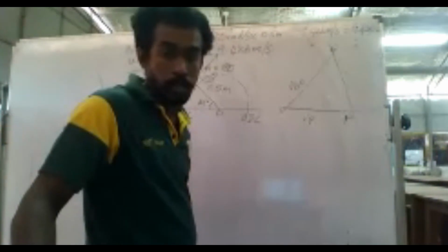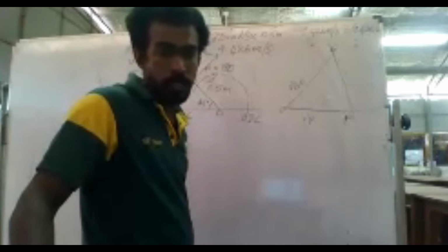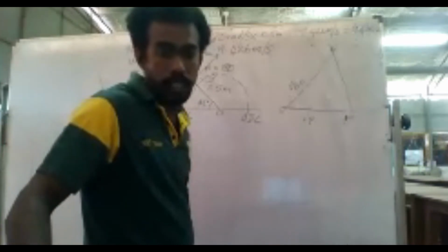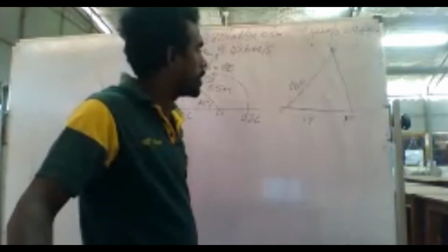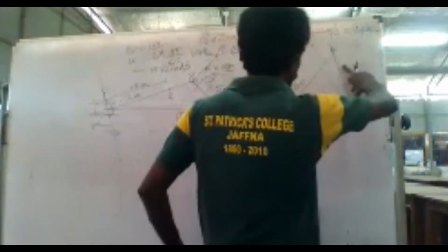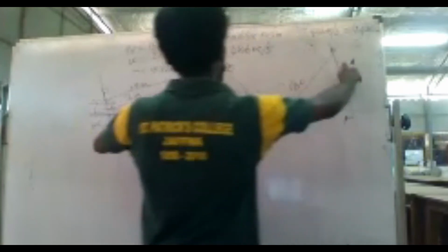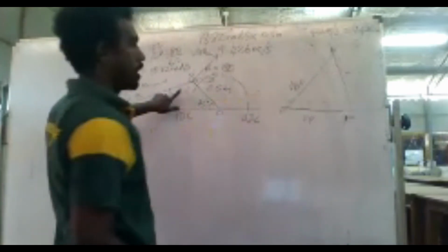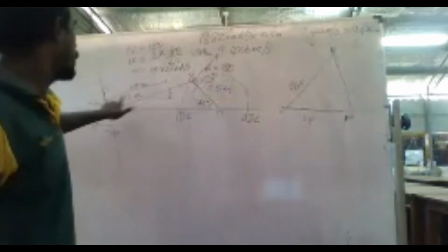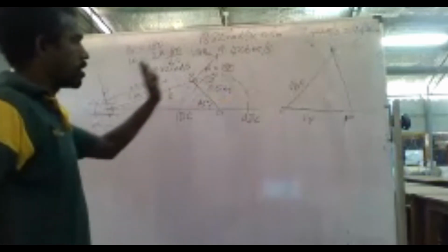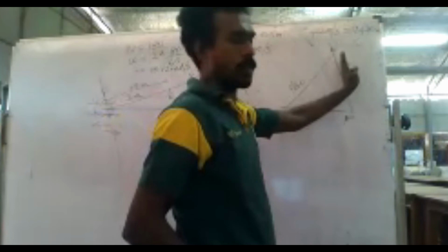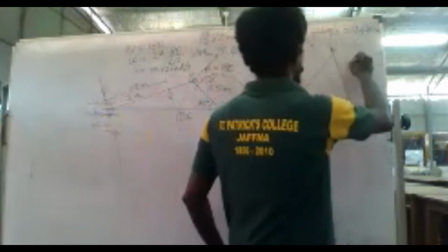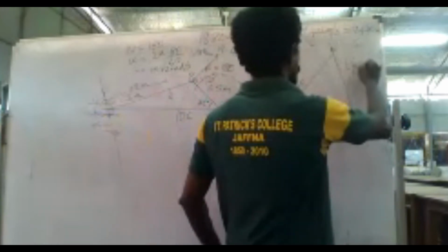Okay. So for the angular velocity of the connecting rod, from the velocity diagram we find the velocity of P with respect to B, VPB. So what you have to do is measure it, right? This is with respect to the connecting rod. PB perpendicular is this. Your measurement of this is going to give you the velocity of PB, right?